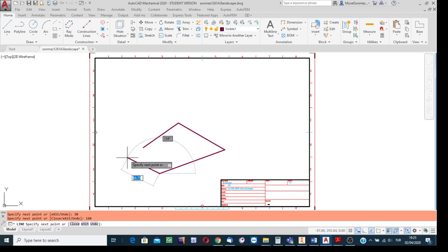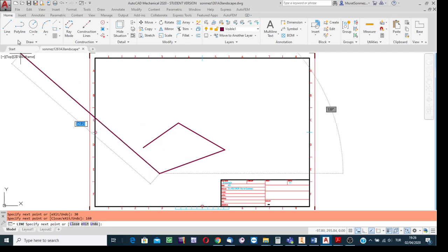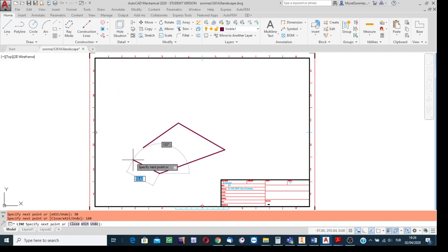Okay, because the boundary lines will be created using the single straight line facility. The lines are in sequence, but when we attempt to apply the extrusion process, the area bounded by those lines will not be recognized as a region. Region definition process is to be applied. You know how? Click on this and then click on this region definition button, define the area as a region. Okay, say that one more line is to be created.